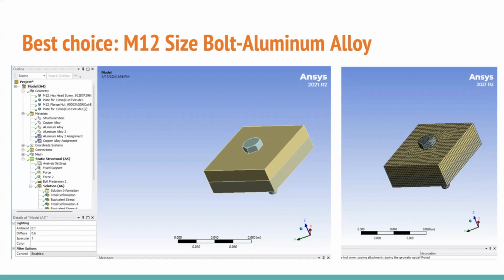But I also did want to touch on the fact that we could also have gotten better results for the factor of safety, possibly a higher, or I would say a more correct value, if our square mesh for our system was better. As we can tell from the picture on the right, on the edges of the actual system the squares were pretty much the exact same size, but as we come to the top of it where the bolt is, we can see that they're starting to disfigure and therefore causing our results to be not as well done as they could have been if we had placed the mesh differently. So that could also have changed our values that we got from ANSYS.